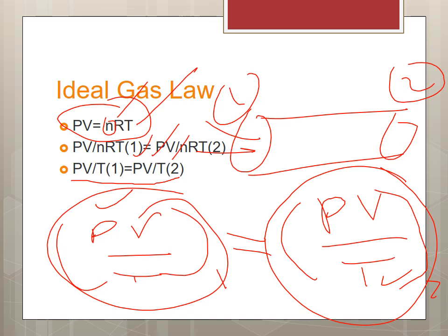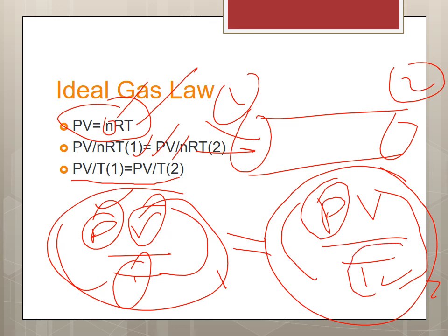So for example, if I have the pressure here, I have the pressure here, and I have the volume and the temperature, and I have the pressure here and the temperature, I can find the volume here. So you have 6 variables, with giving 5 of them you can get the 6th at any point. So it's a good way to calculate gas volume, pressure, or temperature based on the previous situation. So just try to practice the math and going from state 1 to state 2, and this is the extent of what I want you to know in this regard.